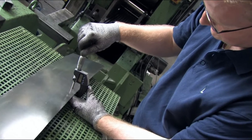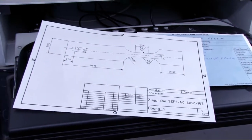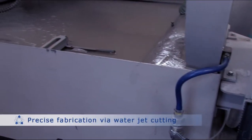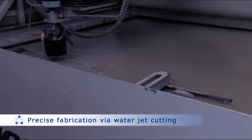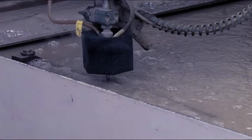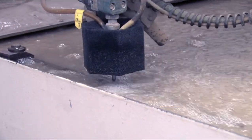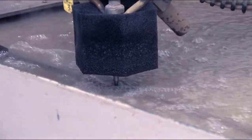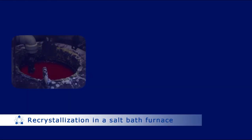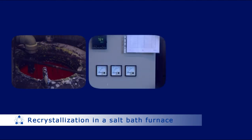The cold-rolled material is delivered by IBF. Here at the Institute of Ferrous Metallurgy, the samples out of ultra-high-strength steels are cut by wire erosion or by water jet cutting. The samples are fabricated with a pressure of 3000 bar. After cutting, the samples are recrystallized in a salt bath.